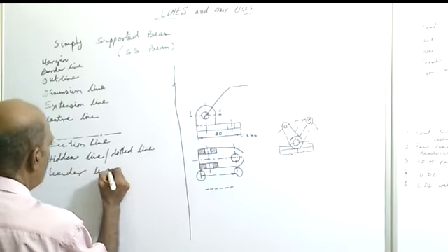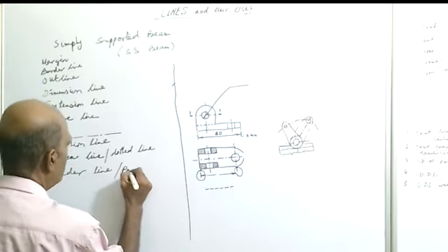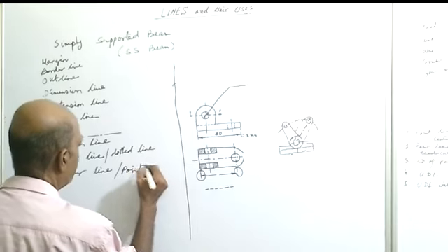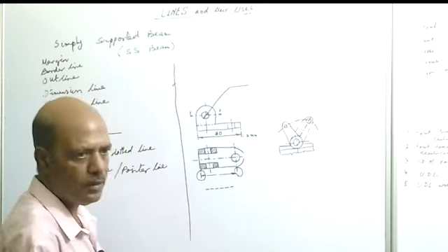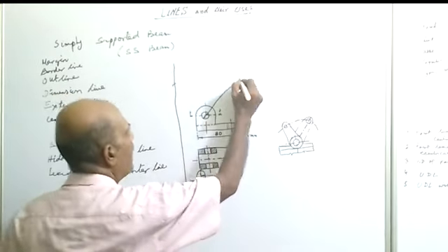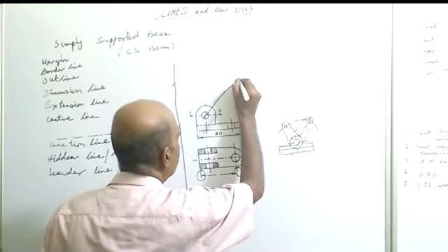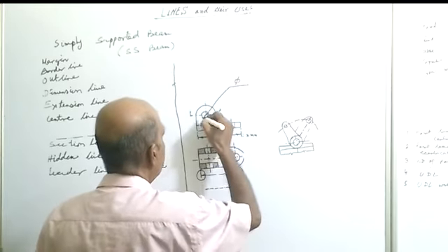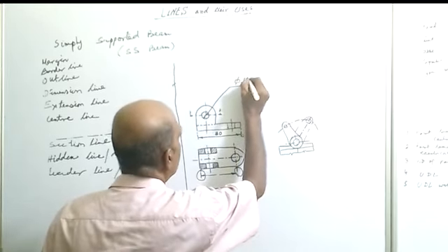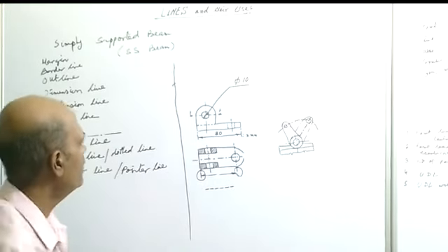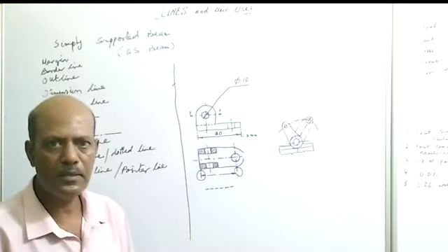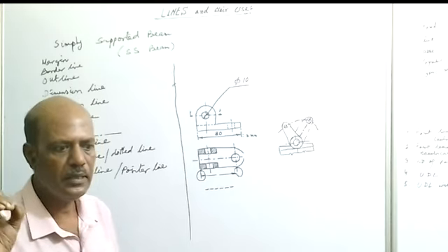It gives additional information regarding the diameter, and diameter is written symbolically as ⌀. Say the diameter is 10 millimeter, so we will write ⌀10. This indicates the diameter of this circle is 10 millimeter.